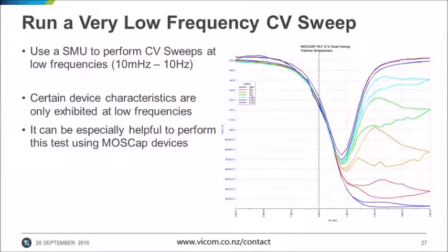As the maximum frequency of 10 Hz is well within an SMU's performance, we use SMUs to get very tiny current measurements. As with all of these tests, the very low voltages and currents involved require 4-wire measurements, guarding, and shielding in order for accurate results. PreAmplifier modules are also of high importance for this test.